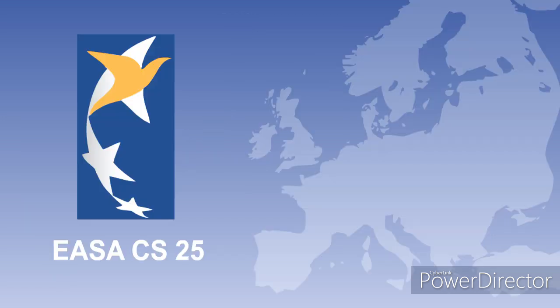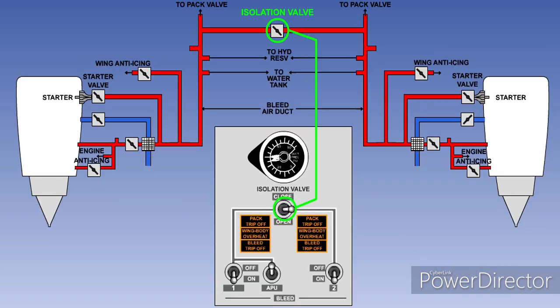It is a regulatory requirement that any single component in an aircraft's cabin air conditioning or pressurization systems, the failure of which could jeopardize the safety of the aircraft or the people in it, must be duplicated. To this end, most multi-engined aircraft keep the supplying engines or sides separate, with each engine supplying its own user services. These are kept independent by isolation valves, which are normally closed, but which may be opened if an engine supply is lost, to feed the other side services.